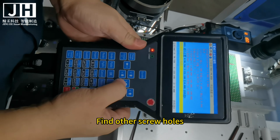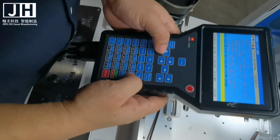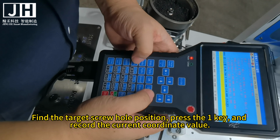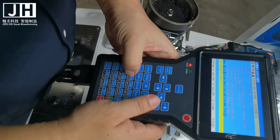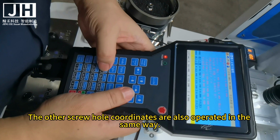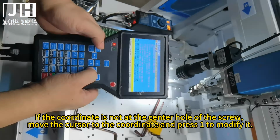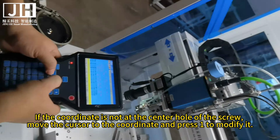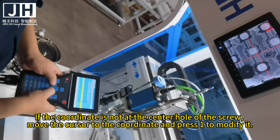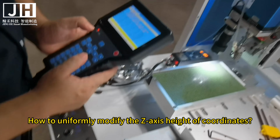Find other screw holes. Find the target screw hole position, press the E key, and record the current coordinate value. The other screw hole coordinates are also operated in the same way. Press E to record coordinates. If the coordinate is not at the center hole of the screw, move the cursor to the coordinate and press E to modify it. How to uniformly modify the Z-axis height of coordinates?